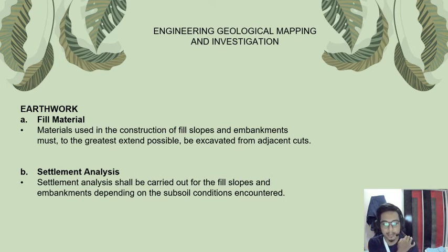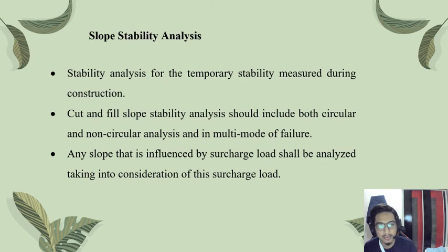Settlement analysis shall be carried out for the fill slope and embankment depending on the subsoil condition encountered. Slope stability analysis. Stability analysis for the temporary stability measures during construction. Cut and fill slope stability analysis should include both circular and non-circular analysis and multi-mode of failure. Any slope that is influenced by surcharge load shall be analyzed taking into consideration the surcharge load.